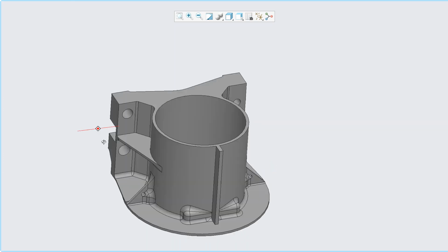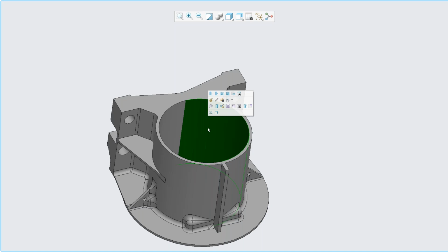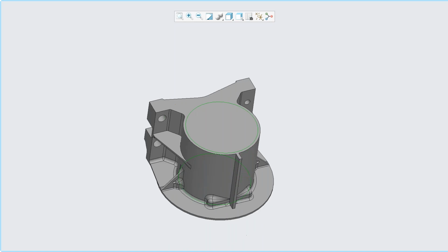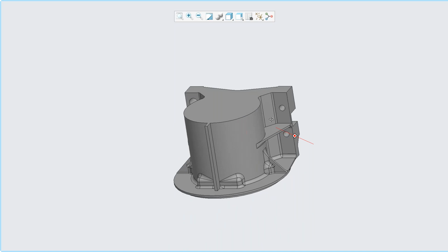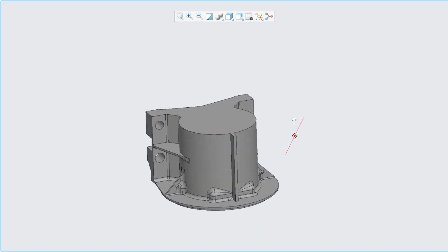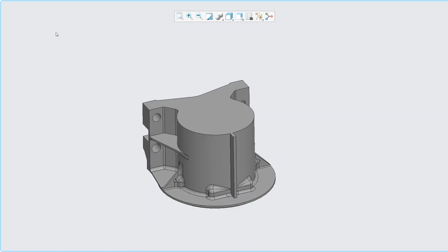Similar to this, I could also say, hey, maybe for whatever reason I didn't want that geometry to be there. I could just say, hey, fill that for me. So what I just did was remove it. I can remove features, right? I don't have to worry about parent-child relationships.